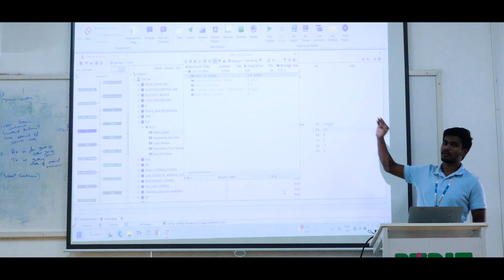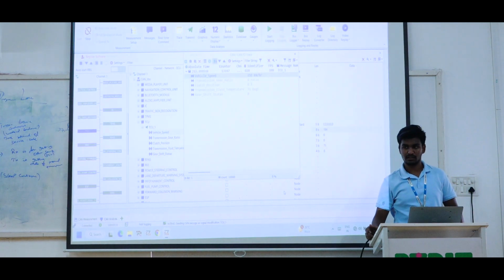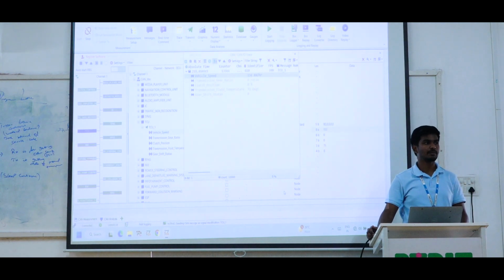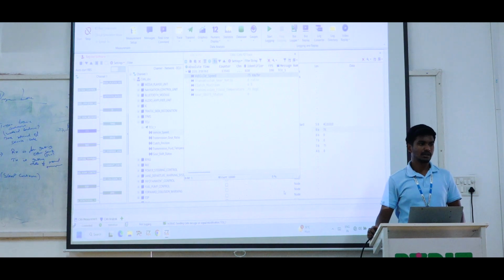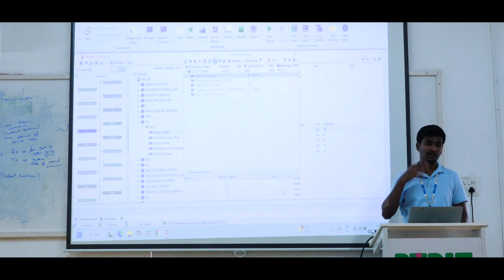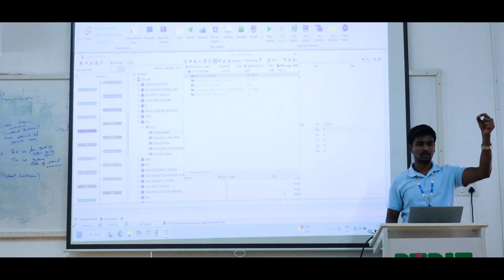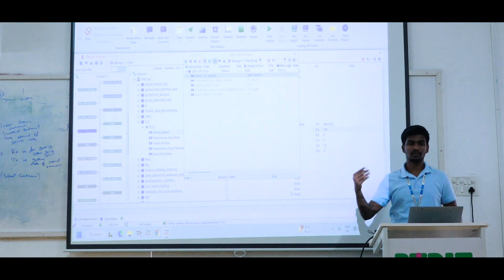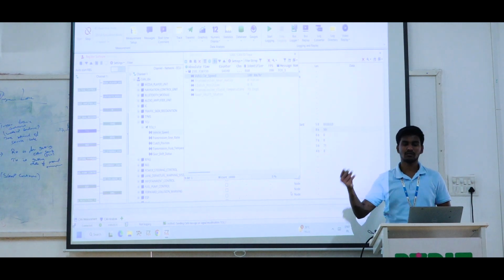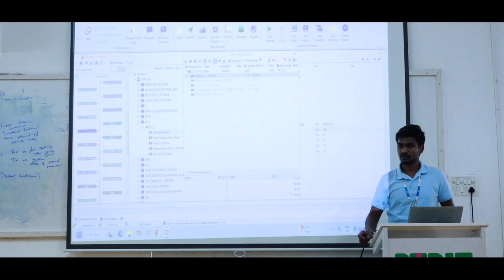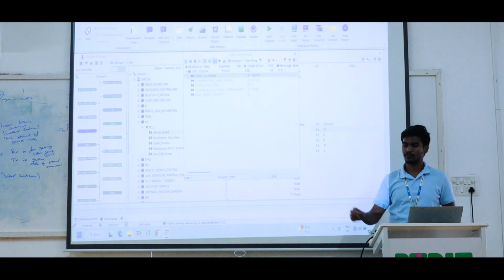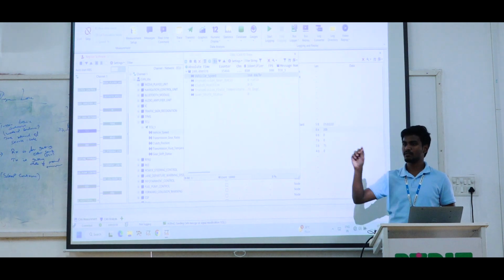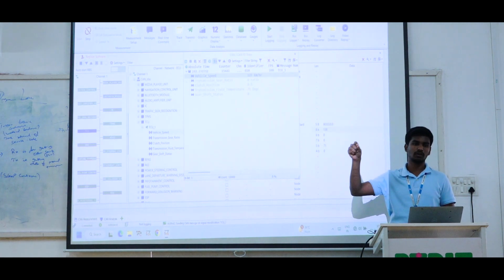But this vehicle speed will not change as per our condition. It is taking the rolling counter values from 0 to the maximum limit, but it is not changing the values as per our requirement. It is not stepping one by one or holding values. These are not defined, so we are going to work with CAPL scripting, using a timer event. The timer event will modify the values as per our requirement. For the value range concept, the value will increase by a step size of 1, 2, 3.